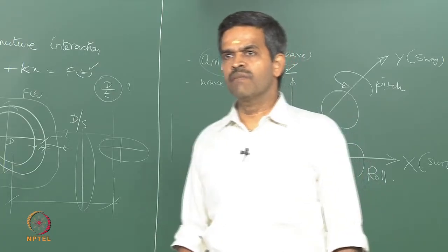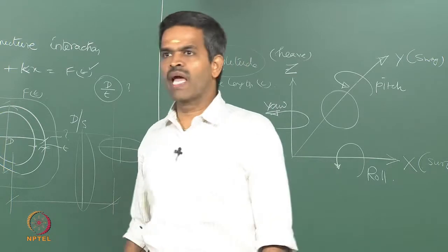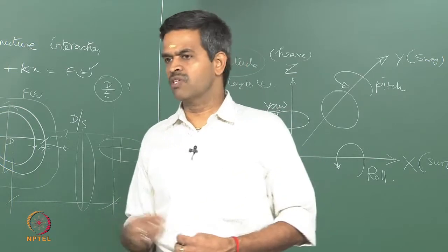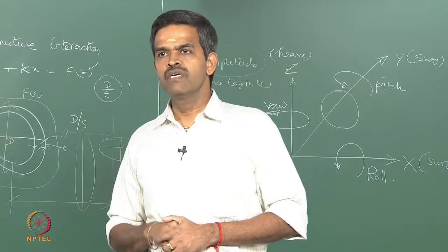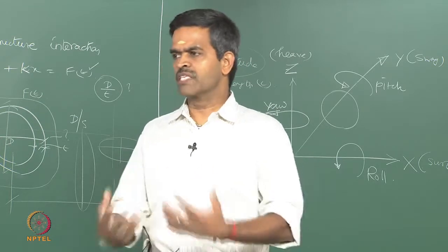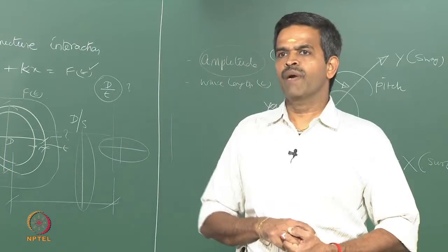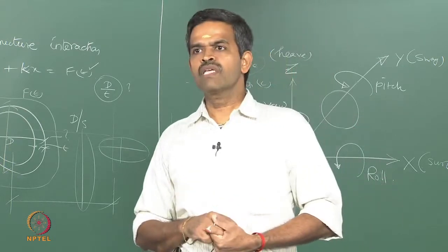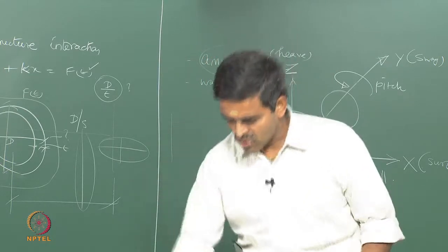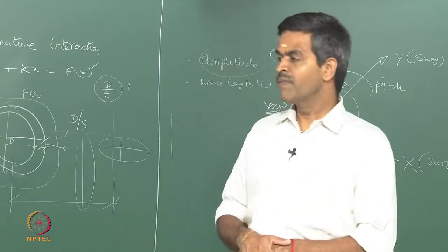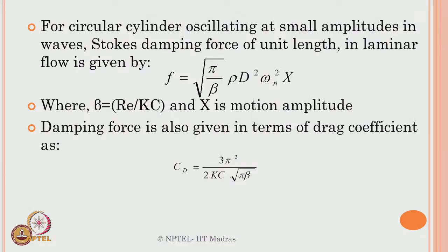Material damping is present in the material of the members and the mechanical connections between the members, or the joints or the connections. This is of course a Coulomb friction model, we already explained this in the earlier module. Material damping generally is small in comparison to the hydrodynamic damping. There are several sources of hydrodynamic damping which we also said in the first module lectures. Now there are two equations available on the screen which will help you to estimate the damping very easily.